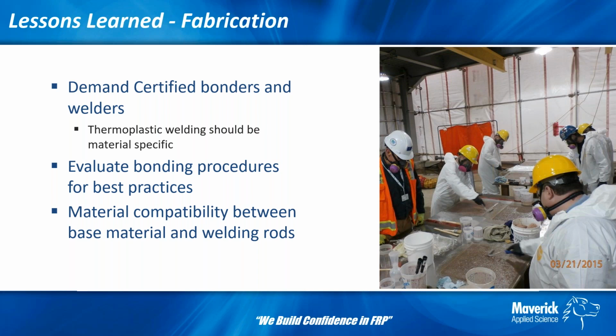So when it comes to fabrication, certified bonders and welders are critical. If it were steel, you'd want to have a certified welder doing the work. You wouldn't allow a welder to work in a plant if he didn't have his current papers showing that he was certified for that material, certified for carbon steel or 316 stainless or Hastelloy or titanium or whatever it might be. They would need to show papers that they're trained and current with that material. And the same is true with FRP and with dual laminates as well. They do have certifications for these, and you should expect that.